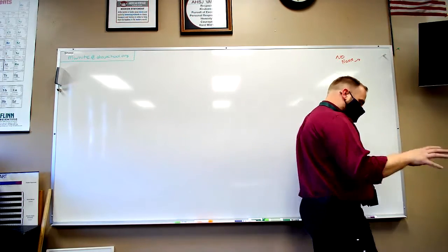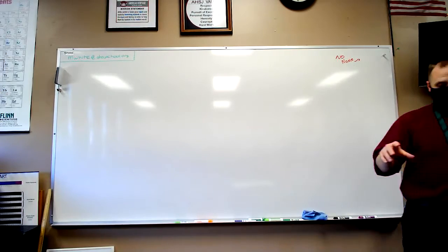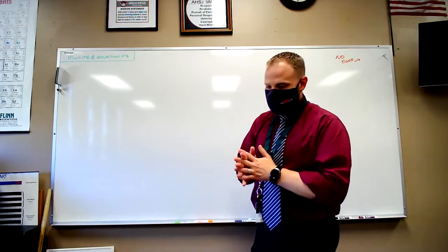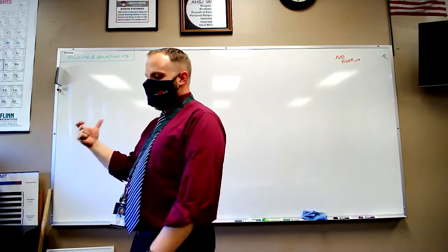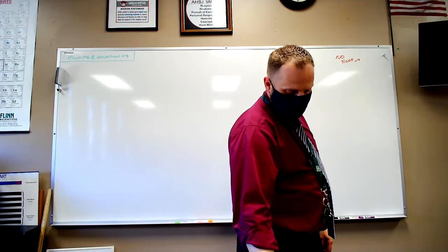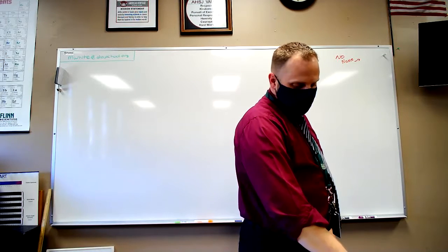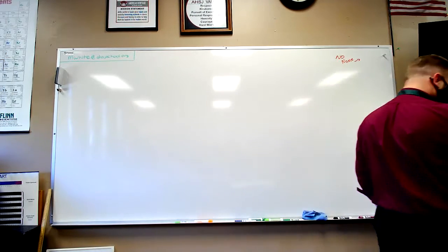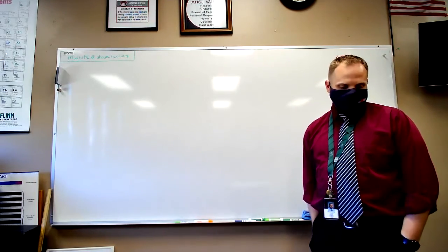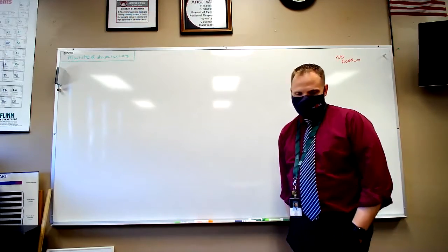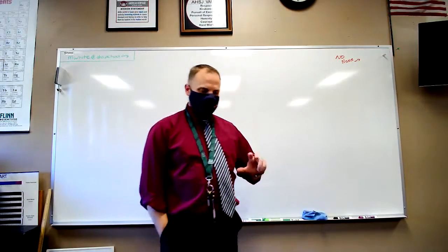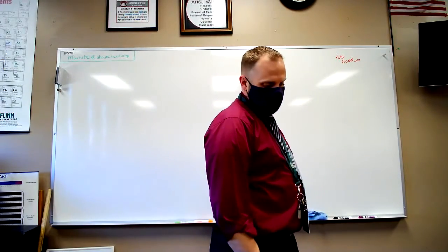So if you have the exact conditions, but one of them is using zinc and one of them is using lithium, you can get about 2.3 volts more from the lithium, and it's going to be lighter. Depending on what you pair this lithium with, it can be either a primary or a secondary battery. So lithium is okay to be recharged, but sometimes the other material that you're working with isn't.